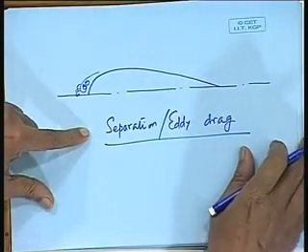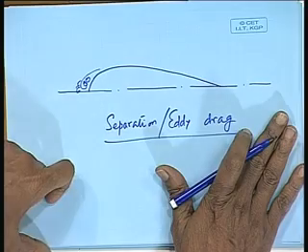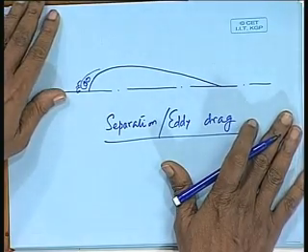Okay. And here you have separation or eddy drag, which in case of a ship is mostly a viscous effect. If it was not viscous, perhaps the flow would have gone around it or some circulation might have been created, but not separation or eddy as we understand behind a ship. Okay. So, primarily now we have seen that for a submerged body you may have some amount of viscous pressure resistance, you will have frictional resistance because all fluids have friction, and you may have some separation or eddy drag.